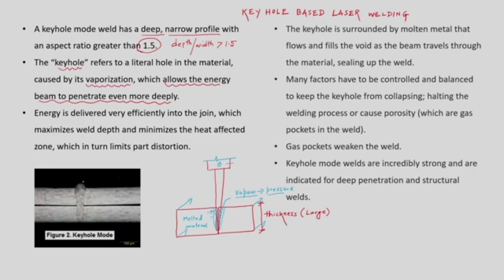So, there is another picture which is there in front of you. Here we are having two plates, plate number 1 and plate number 2. These two plates are put over each other and then the laser beaming is applied. So, you just look at the keyhole which is getting manufactured during this keyhole mode based laser drilling. The keyhole was almost equal to the addition of thickness of P1 and P2.